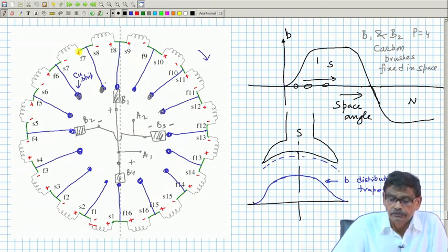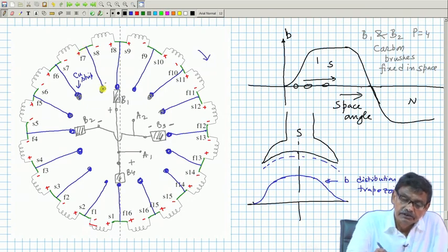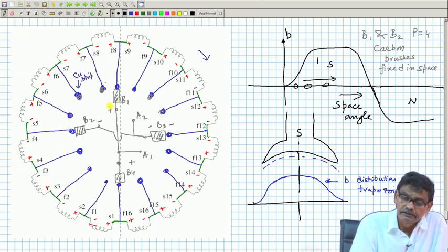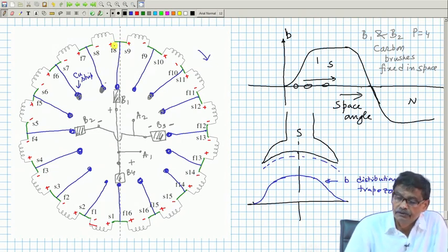This prompted us to think that, okay, in that case I will take from the junctions with the help of conducting wires, terminate on some circular commutator segments, and then I will place fixed brushes in space, which will be stationary, but in which position: where plus plus will be joined, where minus minus will be joined, negative brush here, positive brush here.